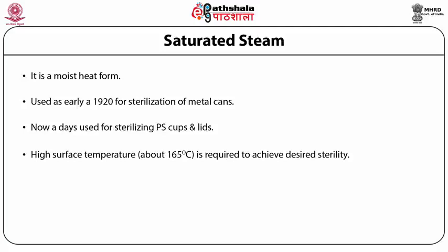Polypropylene cups have higher thermal tolerance, thus they can be treated on the surface at lower temperatures and longer times, 140 to 147 degrees Celsius for 4 to 6 seconds in a pressure chamber. Lid foil can be treated continuously by passage through a pressure lock.